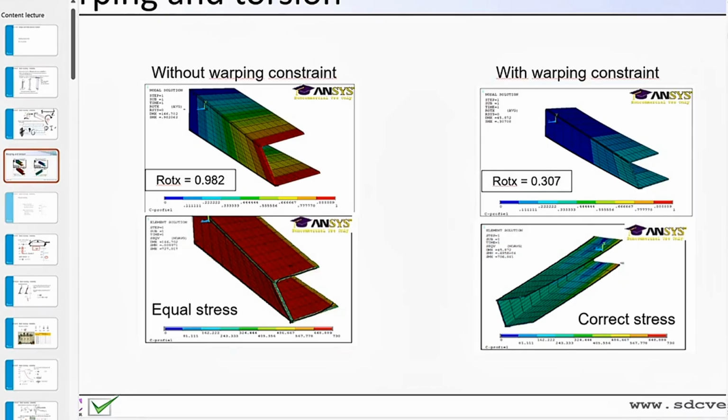So in short, the conclusion is: if you use a beam model and a finite element buckling calculation, this warping is crucial. That needs to be included. The problem is that these things are hidden in the beam properties, so it's not so easy to figure it out.